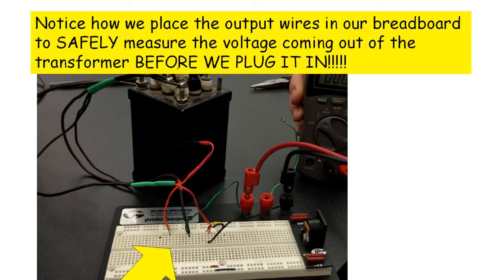What we're going to do is, first of all, you start off by not having it plugged in, and you take the leads coming off your transformer, there'll be 3 of them, and plug them into your breadboard to keep them from flopping around. If they touched, it would be bad. It could cause it to catch fire, and you don't want to touch it yourself. The voltage is not that high, but it's good practice not to touch those.